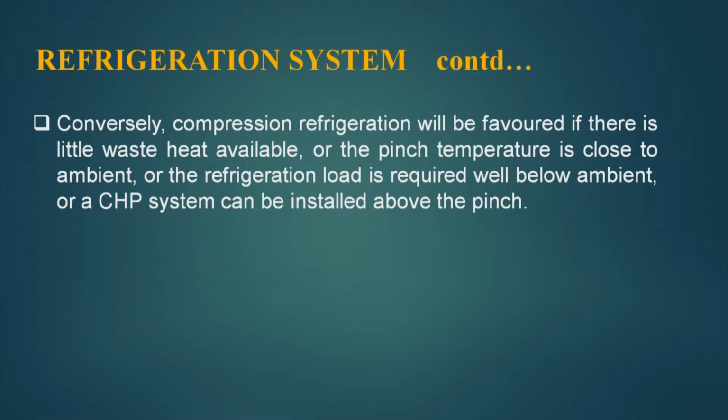Compression refrigeration will be favored if there is little waste heat available, or the pinch temperature is close to ambient, or the refrigeration load is required well below ambient, or a CHP system can be installed above the pinch. So, if these are the conditions, then we can go for the compression refrigeration system, and in this talk we will be using a compression refrigeration system for cooling purposes.